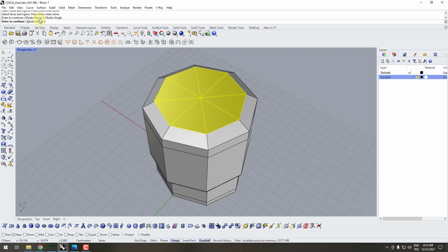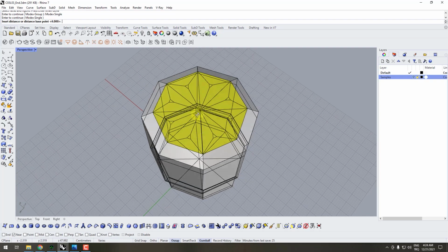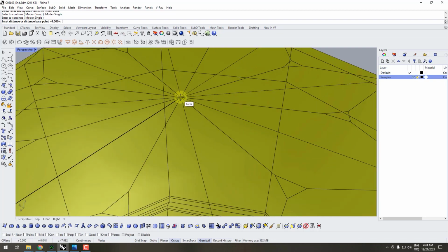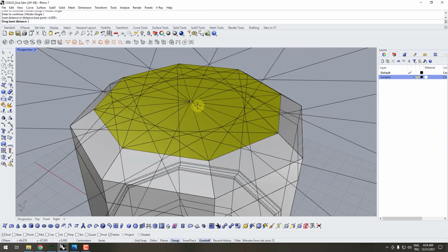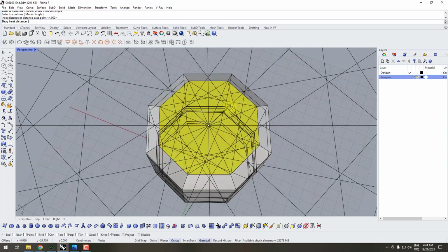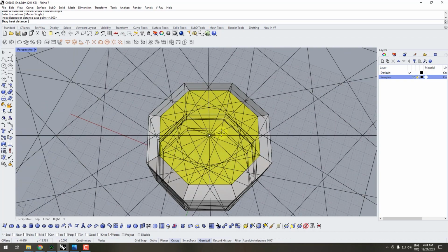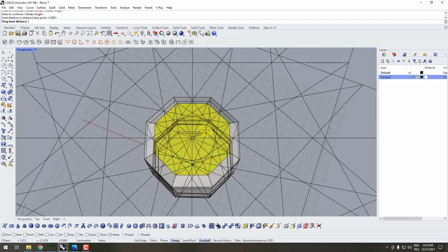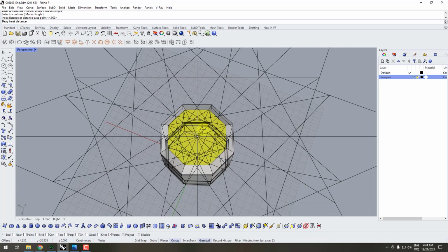I'm going to click here and switch the mode to single mode, and then I'm pressing enter. I'm selecting the base point as the center again. I'm using object snap. Right now you can see every surface I have selected is creating its own inset, and they are creating really big.